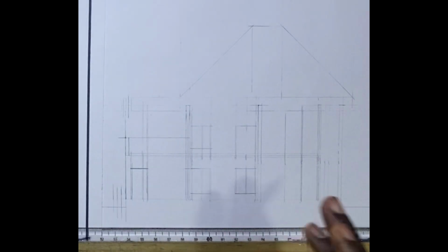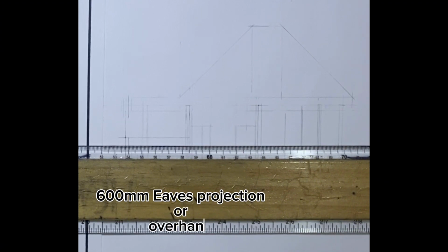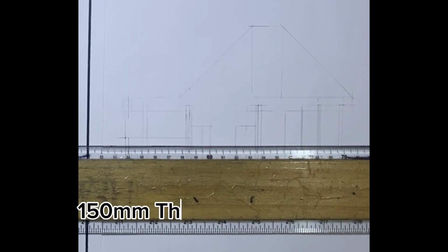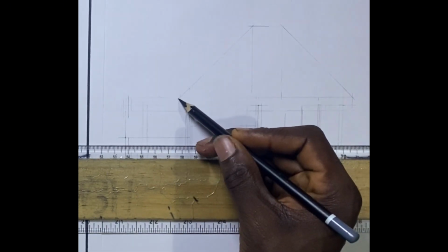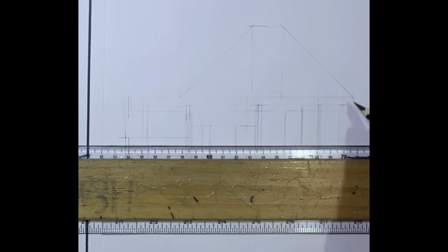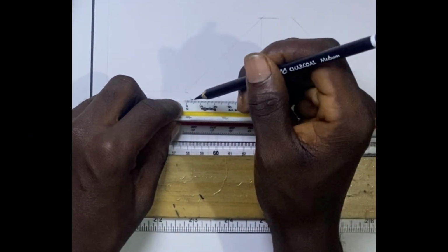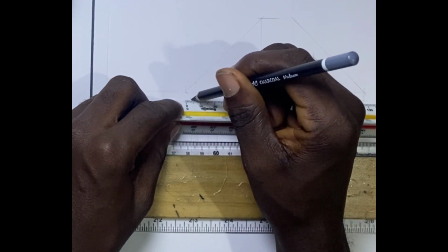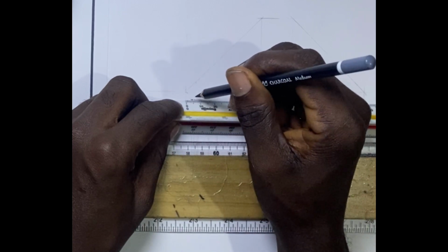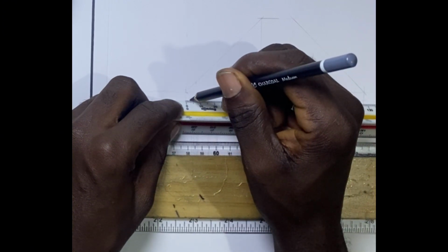First, we'll be working with a fascia concrete of 600 eaves projection and about 150 millimeter thick. For us to achieve that, which will be here and also here at this end, take our measurement. Since we are making use of 1:100, which is quite very small, we take a measurement of 50 from the outside of our wall. Then let's take another 50,